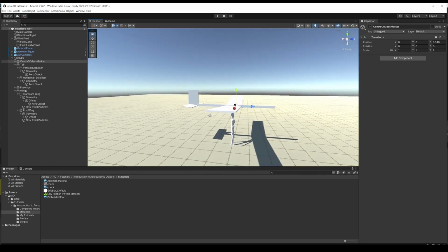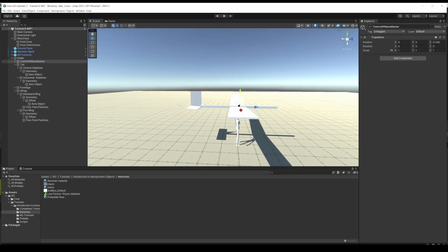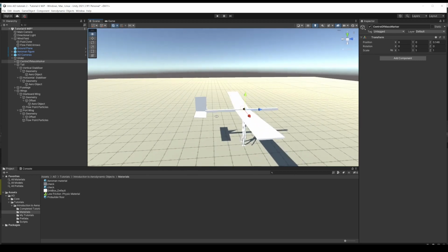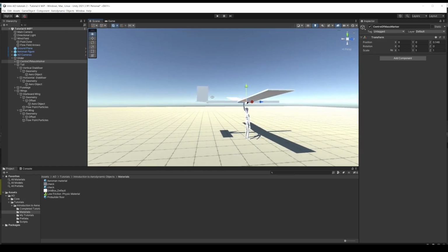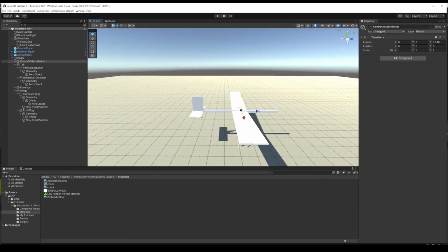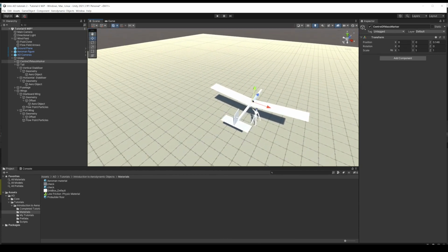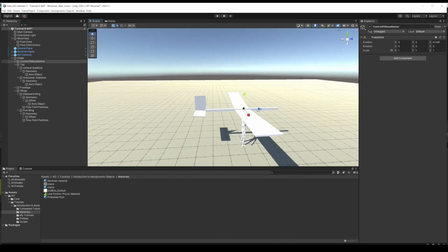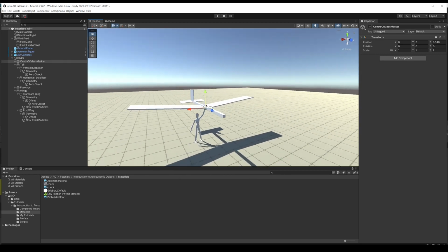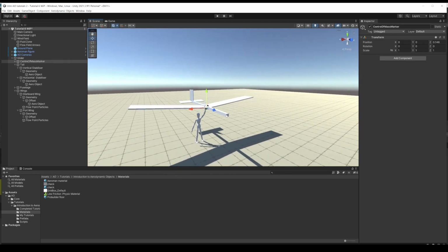And then in terms of flying, we learned that if you don't have any angle on the tail, the plane just basically falls with style. So you need to set some angle of attack of the wing by altering the tailplane angle, in a downward sense. And that will make it fly nicely in a straight line. And then if you want your plane to fly in circles, you have to put some angle on one of the surfaces. So there we go, we've got a fully working plane. It needs some rising air to keep it aloft.